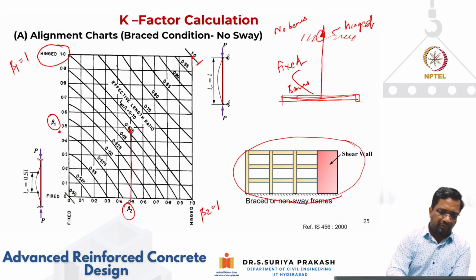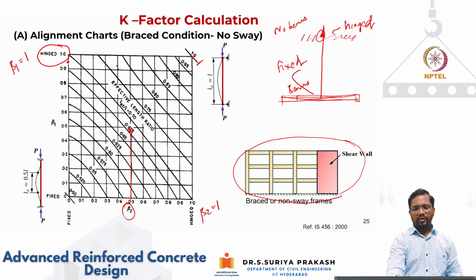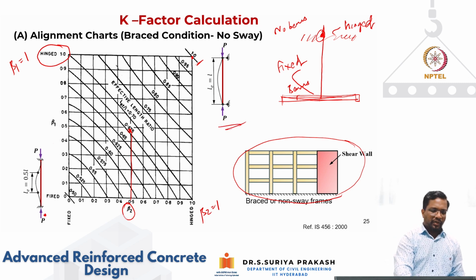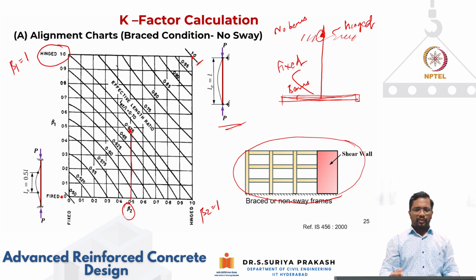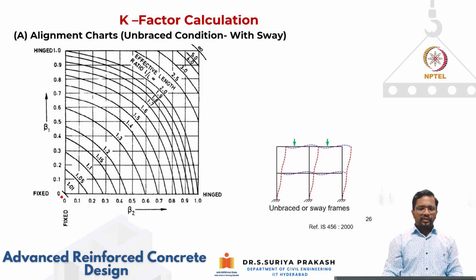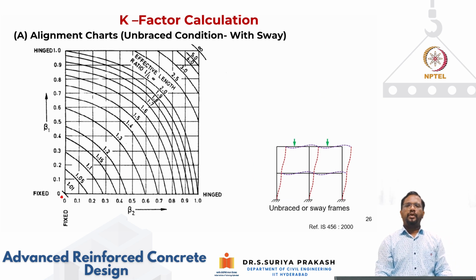So you can have pinned condition or you can have fixed condition. For fixed condition, K is equal to 0.5. For pin condition, K is equal to 1. Similarly, I can do that for sway condition also. So sway condition is this.